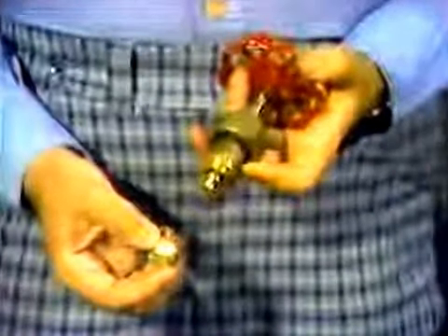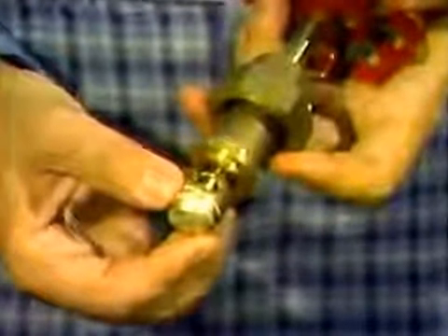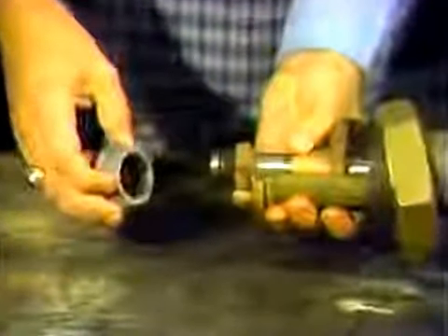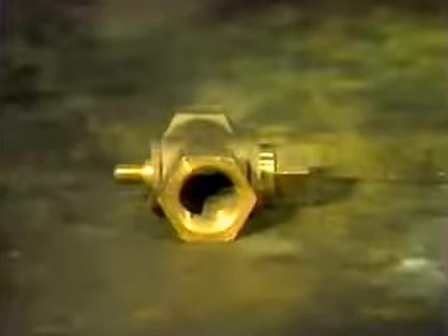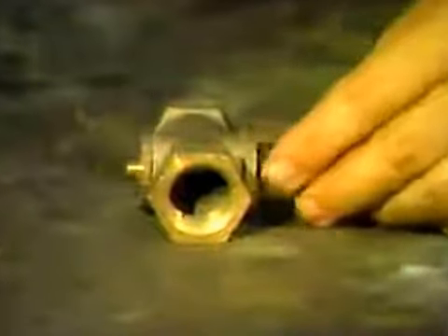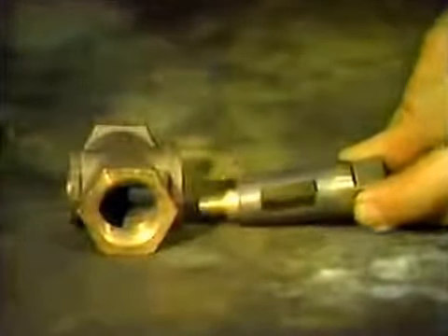There are several ways to attach the disc to the stem of a valve. One way is called the slip-type joint. The disc slips over the end of the stem, and the valve body will prevent the disc from slipping off the stem. Another method of attaching the disc to the stem is threading. The disc is threaded onto the stem like this. Some discs and stems found on inexpensive low-pressure, low-temperature valves are manufactured as one piece and cannot be disconnected.